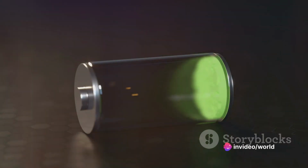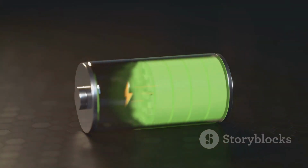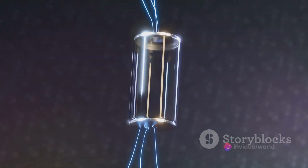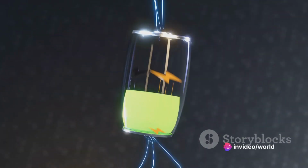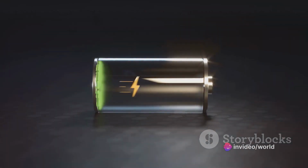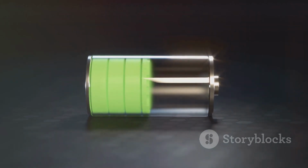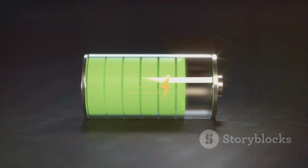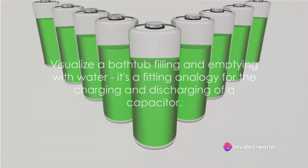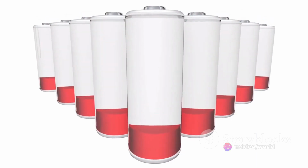The charging curve of a capacitor is an exponential rise, starting from zero and eventually reaching a maximum value, the supply voltage. Conversely, the discharging process begins when the circuit is broken. The stored charge in the capacitor starts to drain out, following an exponential decay curve. The time constant remains the same, guiding the rate of discharge. Visualize a bathtub filling and emptying with water. It's a fitting analogy for the charging and discharging of a capacitor.